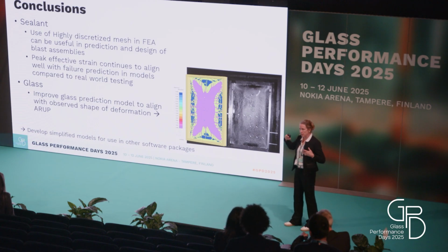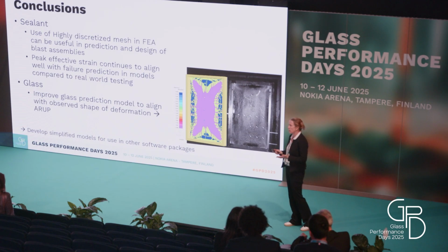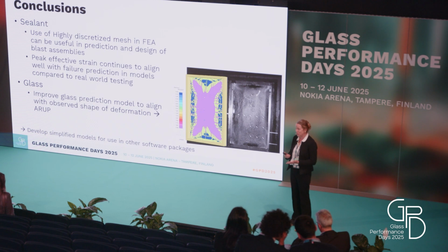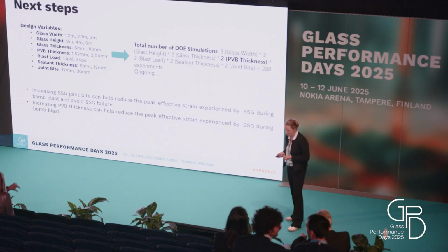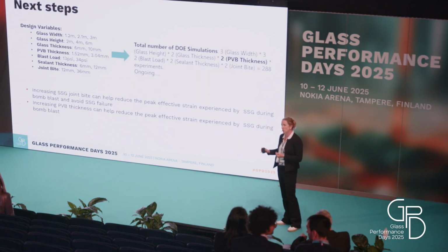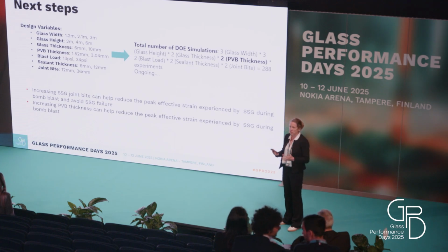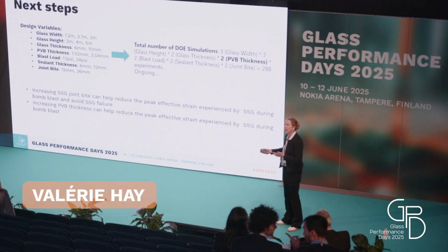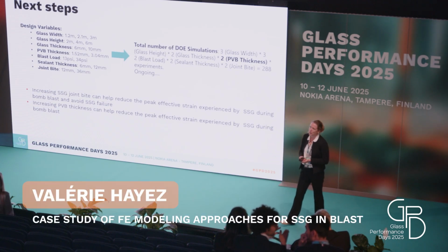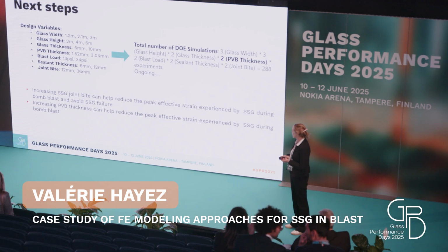Still, it's interesting, this FEA, but it's very heavy. We, TS&D, the support people at Dow, need simplified approaches that will allow us to give very busy industrial people a quick answer. So we are trying to bring that knowledge in a simplified format that can be used directly. As usual, we are currently running a parametric analysis, varying a maximum number of parameters, the glass dimensions, the PVB, the joint dimensions, so that we can, after that, extract some empirical analytical equations for the joint dimensioning.